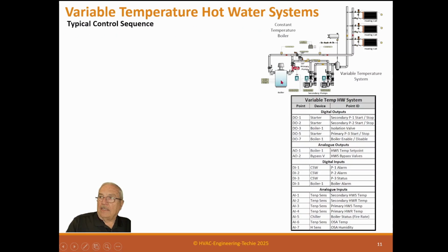And what it has is one boiler, maybe two boilers, and there's a primary pump on each boiler. So each boiler has its own primary pump, and it's connected with a loop. So if this is flowing less water, this primary pump will pump like this. If these are flowing more water than this, then they pump like this. And this is a decoupler.